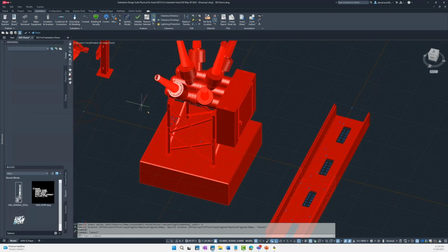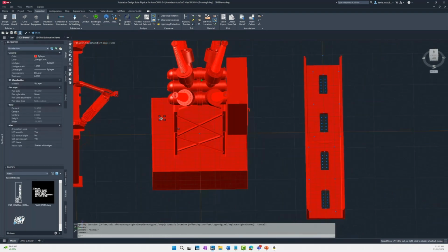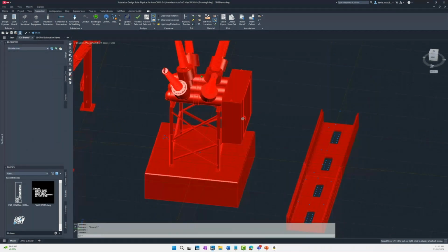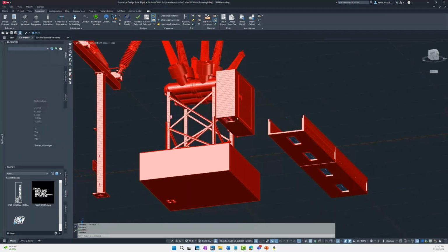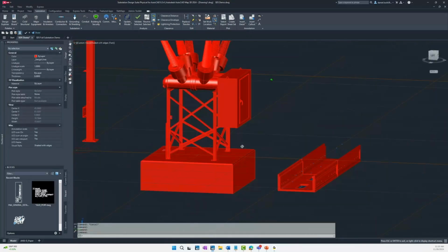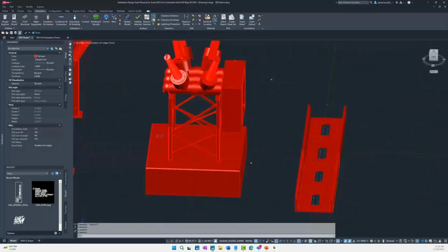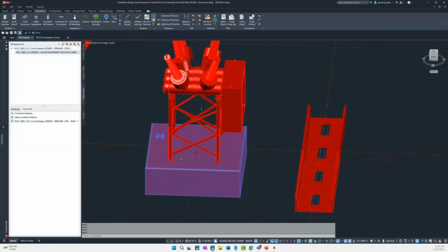But one quick thing to note, I see that the conduit punch outs on our foundation are not aligned with our breaker. On the underside, we want to make sure we align that with the conduit knockouts for our breaker panel. So this can easily be adjusted by selecting the foundation. We'll go to our dashboard, and again, there's that containment.